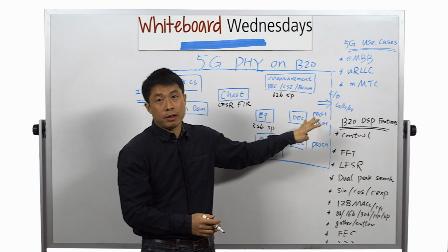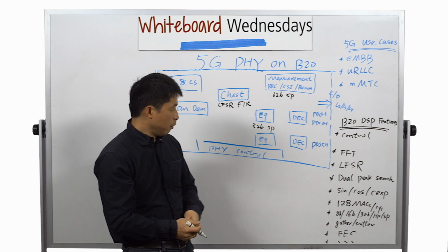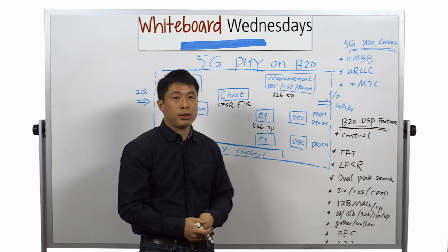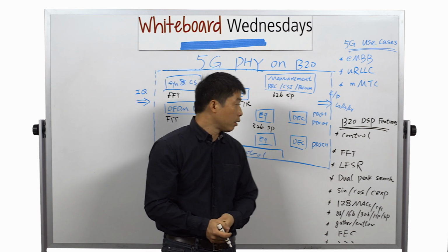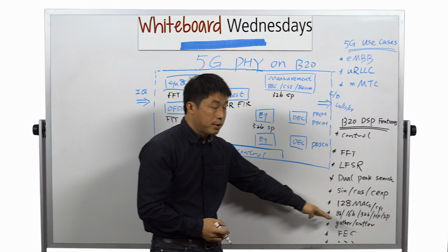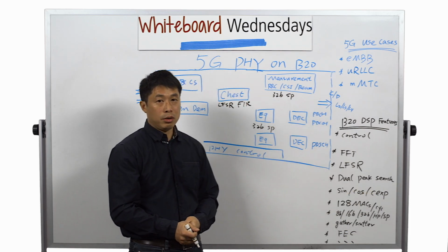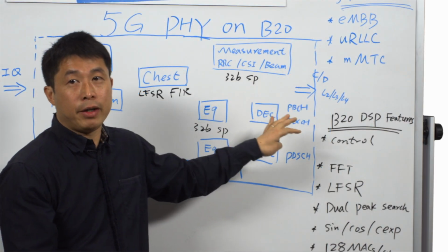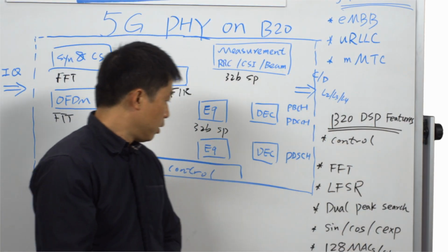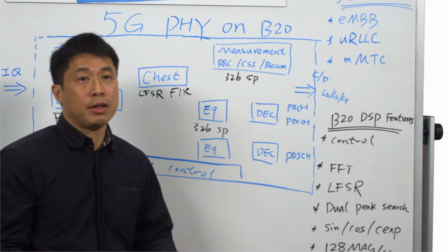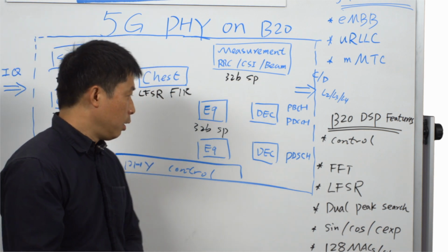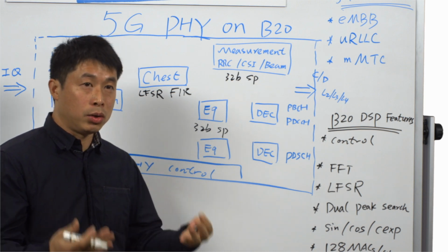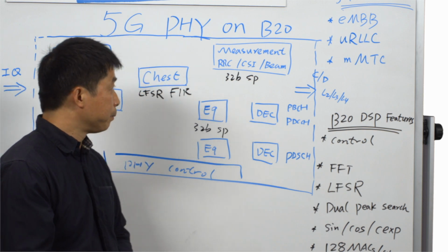And for the soft information, it is 8-bit. So we also have 8-bit support on the DSP. You can use 8-bit instructions to do rate matcher, interleaver. We also have the gather scatter feature on the DSP. You can do interleaver kind of algorithms. We also have the FEC accelerator on the DSP, but we are only targeting low throughput and medium throughput. If you have a 1 gigabit per second kind of use case, probably you still want to do the decoder in a hardware block.